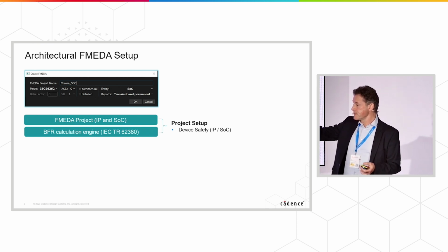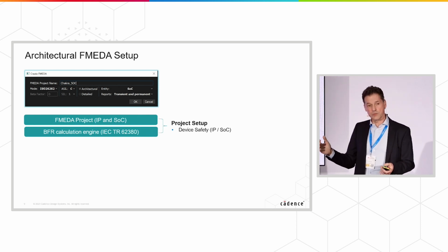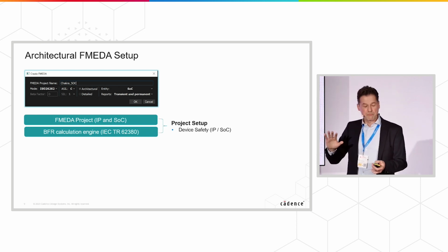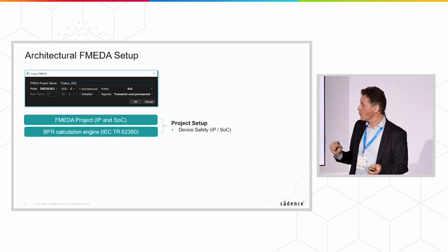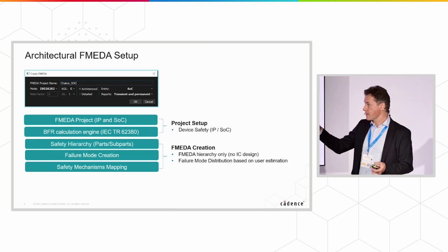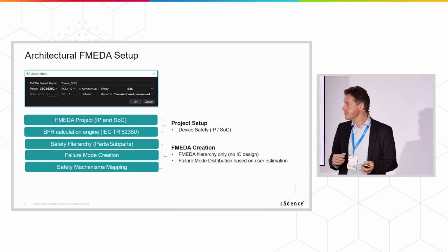Within MIDAS, there's a base failure rate calculation engine that allows you to calculate the failure rate, and I will cover later on what is the input in order to do so. And this base failure rate calculation uses the IEC TR 62380 standard.